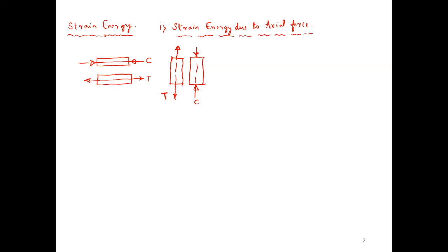It is a hinge jointed structure. What is meant by pin joint? What is a hinge? There is no translation. Hinge will allow rotation, but it will resist only translation. Translation means only axial forces. So these kinds of forces, only axial force, in which kind of structure? That is truss.